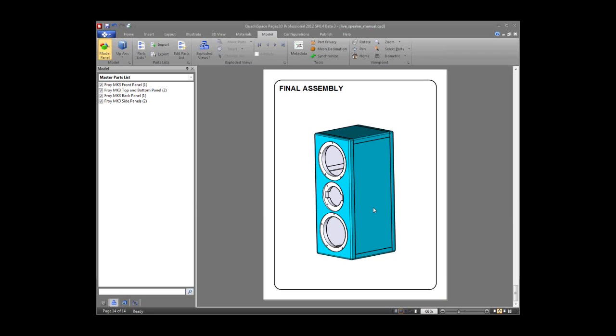Let's see. Can you create a kit of parts within the parts list? I might have addressed that with the configurations. You can. I guess another part of that question could be merging rows. If you have a number of parts that are in a kit, like you're saying, you could go into the parts list editor, select those 4 components that are in the kit, merge them, and rename it to the kit. So you can do that from that perspective too. Another way to do it is through configurations.